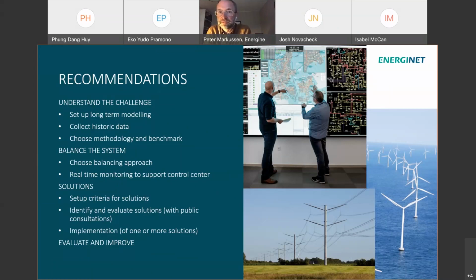Then to balance the system, choose your balancing approach. How do you want to do it? Is it reactive, proactive? How is your system built up? Where do you have your congestions in the system? And then have the real-time monitoring to support the control center, but also make sure that they have some solutions, some tools that they can use when they see the challenges.